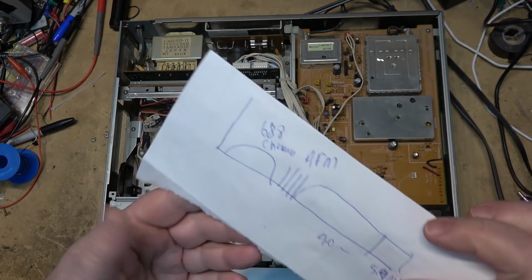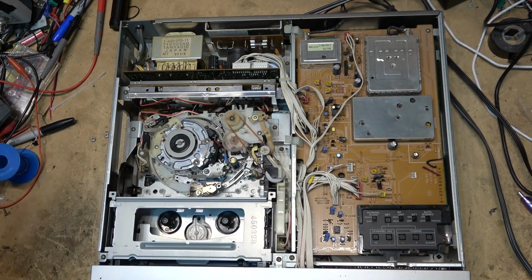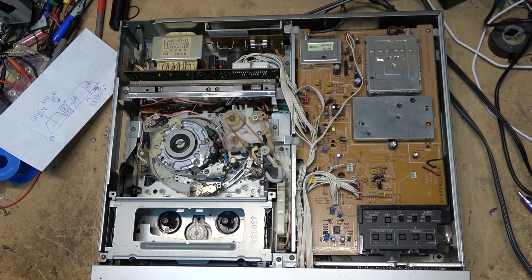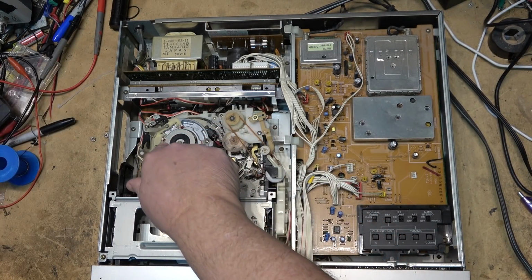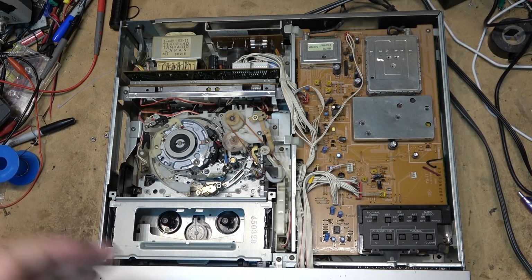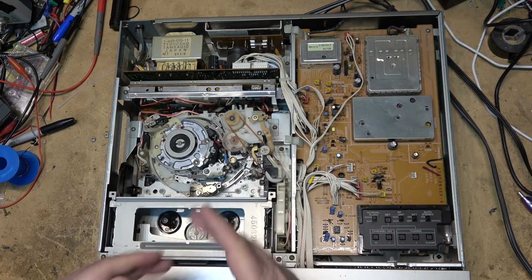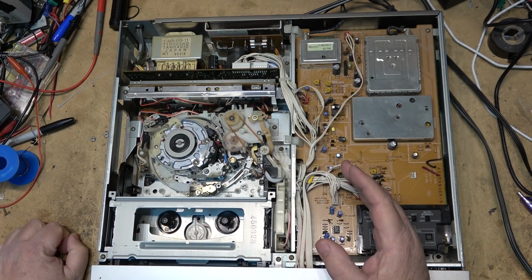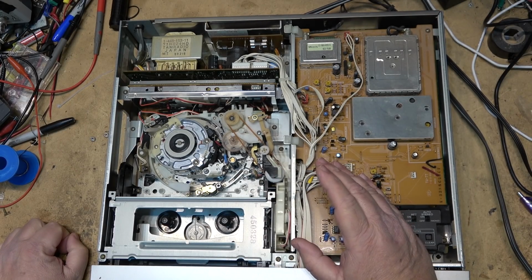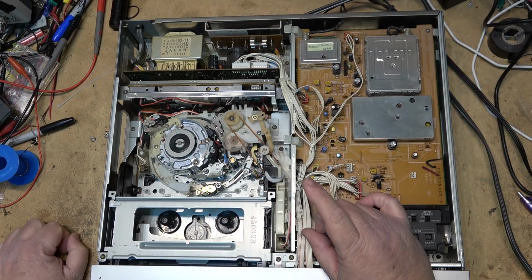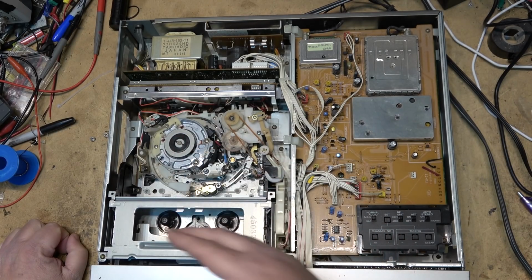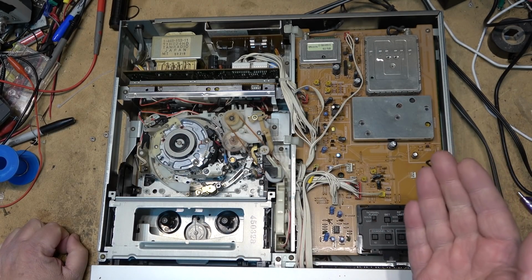The PAL machines rolled off, I think it was around 3.6. The carrier was lower on PAL, because the head drum is spinning so much slower, 1500 RPM versus 1800, so they didn't have the available bandwidth that they could shift the carrier up. So what the PAL system did was the same thing that VHS did, and that was go to deep layer recording with a second pair of heads that recorded at a much different angle.